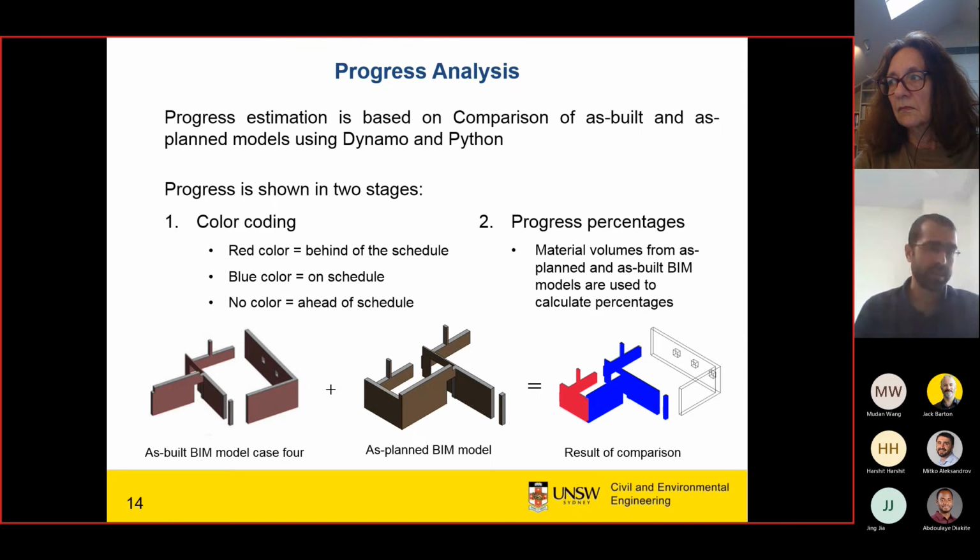This is the second. And the third one could be using this handheld scanner. As you know, with photogrammetry methods and terrestrial laser scanners, when you cover a construction site to measure the progress, you need to install several of them to cover the entire site, otherwise it will be difficult to understand the progress. So using a mobile device compared to a static one will help a lot, because it will be simple and you can cover the entire site.